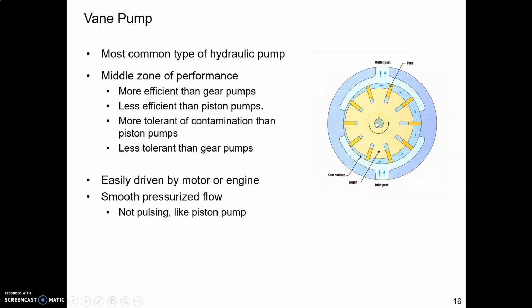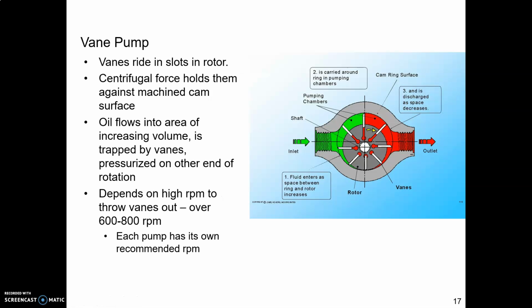and this too is off-center, like in a gear pump. And so these cavities fill with oil, and as the thing turns around, it's under pressure and the oil gets squeezed out the outlet. So these are fairly smooth running.